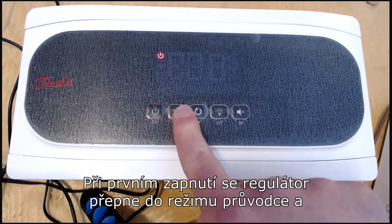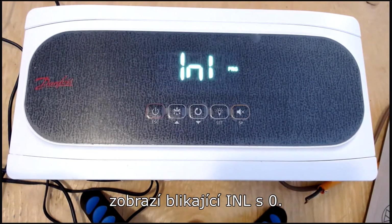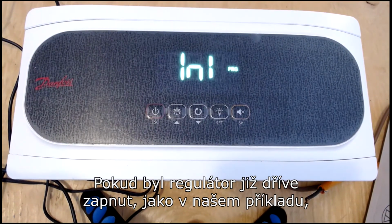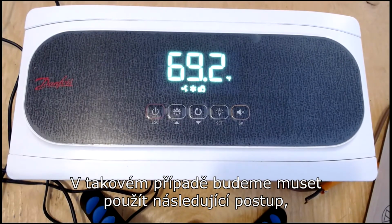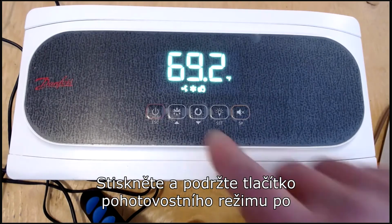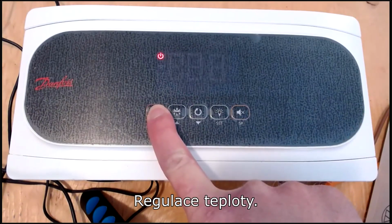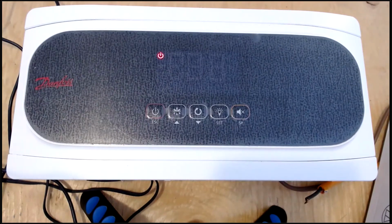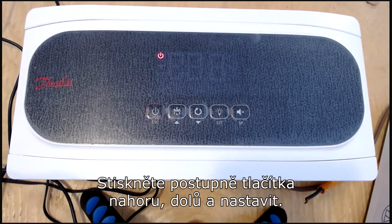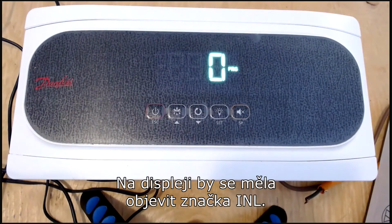When the controller is first powered up, it will enter the wizard mode and will display INL, flashing with 0. If the controller has been powered up before, as in our example, the wizard will not start automatically. We will then need to use the following procedure to start the wizard again. Press and hold the standby button for 3 seconds and wait until the unit completely halts temperature regulation. Note that the indicator light will light up permanently. Press the following keys in sequence: up, down, and set. The INL sign should appear on the screen.